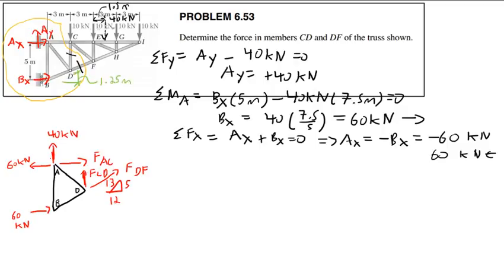Well, each of these bays, I don't know if the word bay can properly be applied to a triangular section, but whatever, I'll call them bays anyway. Each of these, from A to C, C to E, etc., is 3 meters. So the total horizontal distance is 12 meters. So each of these represents 1/4 of the total horizontal, which means since this is the same triangle, each step here must be 1/4 of the vertical. 5/4, 1.25 meters.